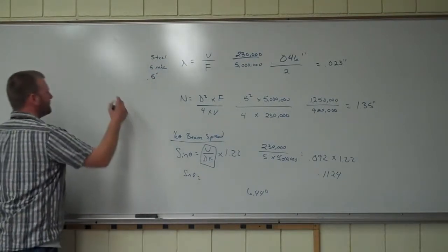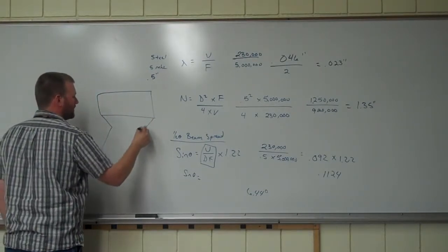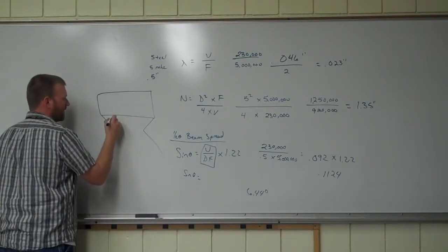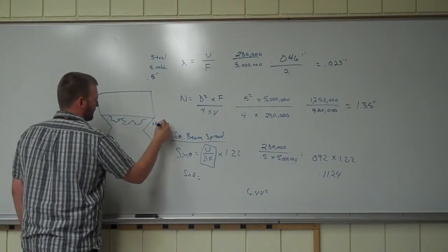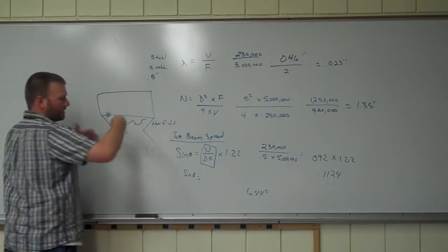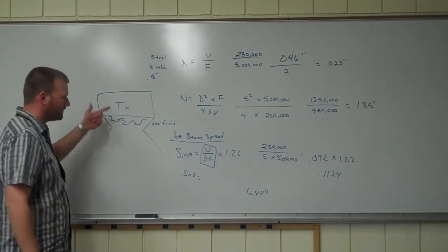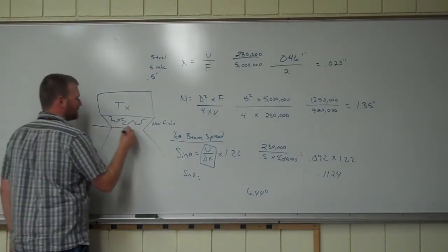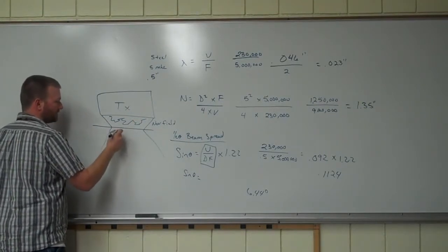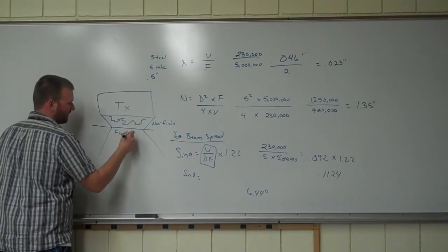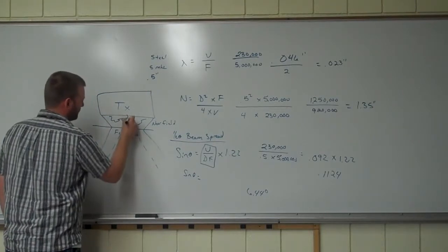And really all that means is this. Here's your transducer. The beam comes down, kind of cones in, cones back out. Inside of here, all of this area where the waves are inconsistent, that's the near field. All the waves are in there, but they haven't really done anything for us yet. There's constructive and destructive forces happening in there. Once they've completed that near field and got their uniform wavefront, all of this down here is the far field. And this is where our beam spread comes from.